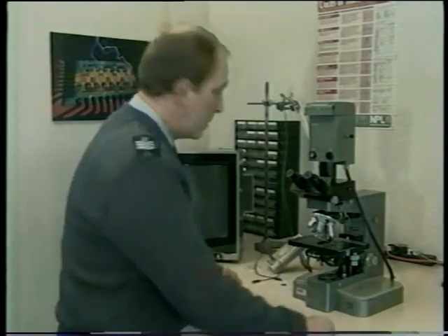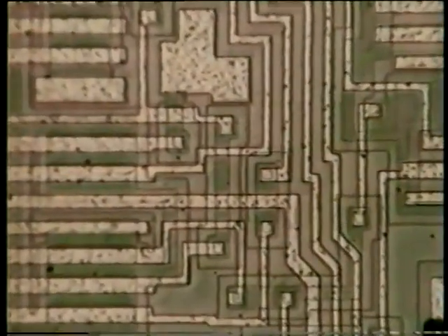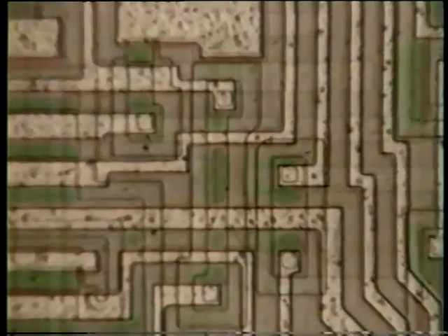Have a look at this. This is magnified by about the same amount as being able to see a car from a satellite. These devices are so tiny that they cannot handle any current or voltage much greater than the normal operating levels. With an electrostatic discharge, or ESD, a current of tens of amps or more can pass, if only for a very short time. And this current can damage the circuit in the same way that an overcurrent would blow a fuse.